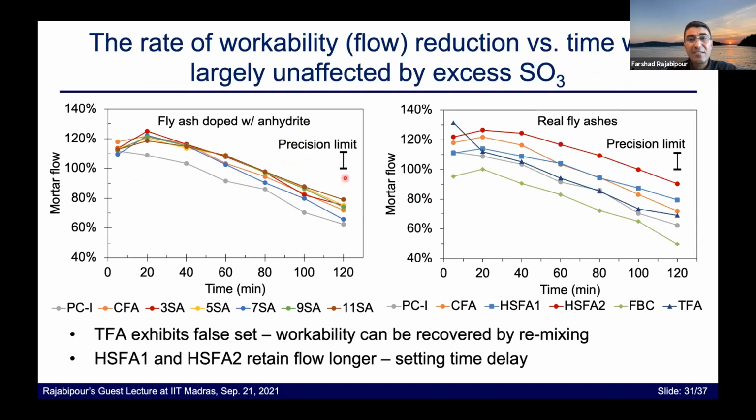We also looked at the flow retention or workability reduction versus time for both doped fly ashes and real fly ashes. The short story is that the slopes of these lines are more or less the same. The lines are parallel. So you may start at a slightly higher or lower flow, but the flow reduction with time is more or less the same, irrespective of the SO3 content.